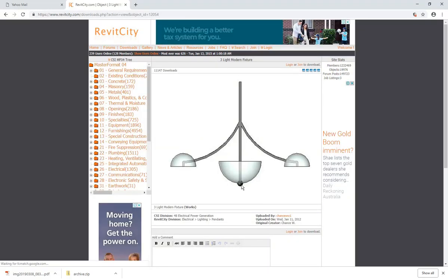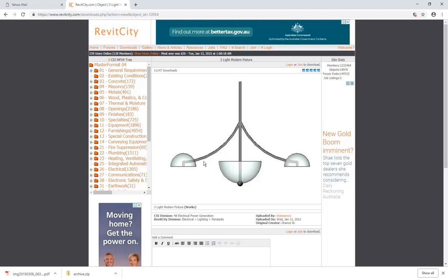Yeah, ugly, but look, it should work, and they normally are set up to actually give you some light when you render. So how do you know if that's set up? Oh, you have to download it and then try it out. That's the only way. But then what you'll often find is that they maybe will put the light fixture or the light emitter inside an object. And so if you render and you realise it's not giving you any light, then you can check to see if that yellow emitter is inside something that's solid, and then you can just move it, and that should make your lights work.